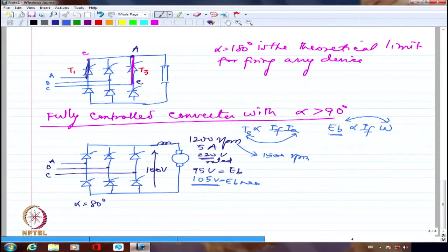So if I have to stop it, in that case, only way I can do it is to feed the power that is being generated in this machine. I'm calling this as a machine now, not motor. I have to feed the power that is generated because of downward movement of the machine, which is working like a kinetic energy generator. So the machine will essentially start generating power.